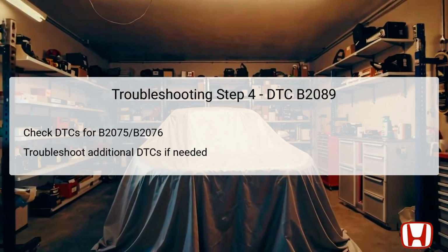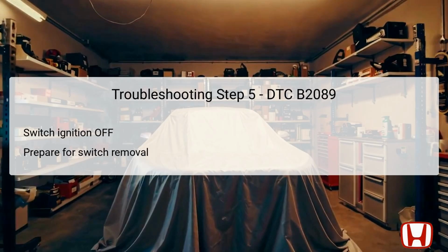Such codes can provide valuable insights into whether the issue is localized to individual doors or indicative of a broader system failure. Comprehensively diagnosing all relevant DTCs ensures that no underlying issue is overlooked, maintaining the operational integrity of the sliding doors. Once assessments from the previous steps are complete, the technician should turn the ignition switch to the lock position or select the off mode by pressing the engine start-stop button.